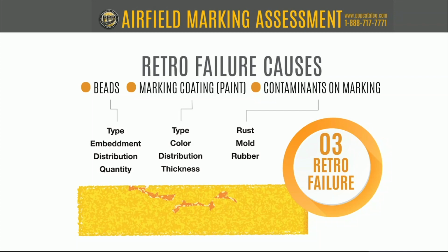I want to focus on paint distribution, kind of as Mike did. It's extremely important that your lateral thickness is as consistent as possible, especially with thinner coatings like type 2 waterborne paints. I often see folks use architectural spray, airless spray tips. That's generally a black tip, depending on which machine you're using and what brand tips.